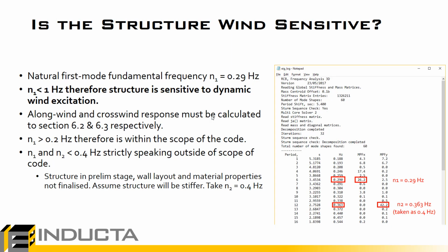Now, what about C dynamic? So the first question that we have to ask ourselves is, is the structure wind sensitive? In the previous frequency video, we saw how to generate a frequency report, how to get the frequency values, and we use that frequency report to determine if our structure is sensitive to dynamic wind excitation.